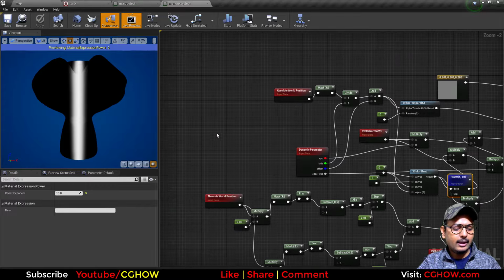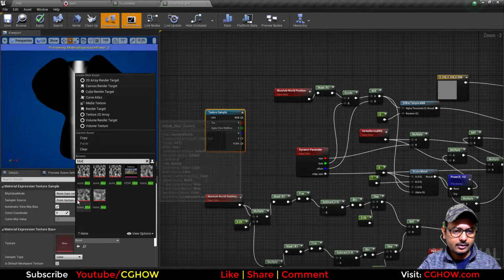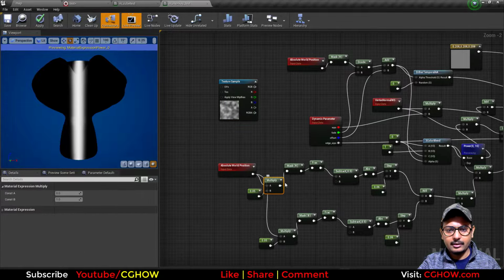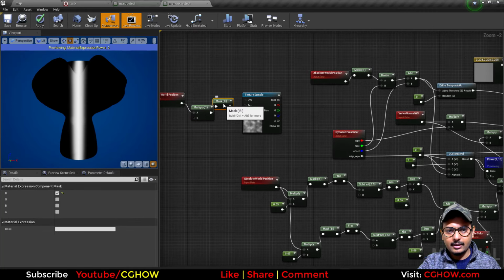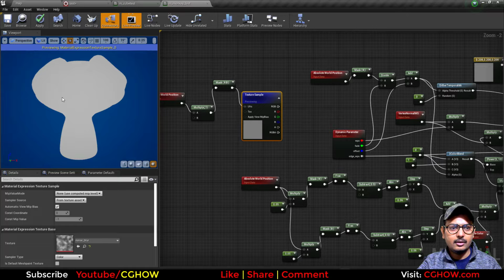So what I'll do, I'll take a texture, I'll take a blur noise texture, I have already this, and then I will take the world position offset, copy with multiplier, and these 3 things I'll copy and paste here, and I'll use the green, red and blue channel, so this will be visible on a world space.